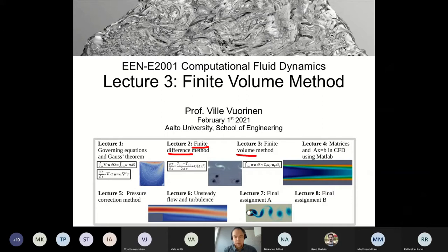So as I mentioned last week, on uniform computational grids, these methods commonly boil down to the same method. So finite volume method is mostly needed when you have different elements. If you divide your computational volume into, let's say, arbitrary polyhedra or stretched or somehow skewed elements, in that case, finite volume method would be the method that works. Finite difference method is typically intended only for uniform and orthogonal grid types, when you have rectangular hexahedral elements.